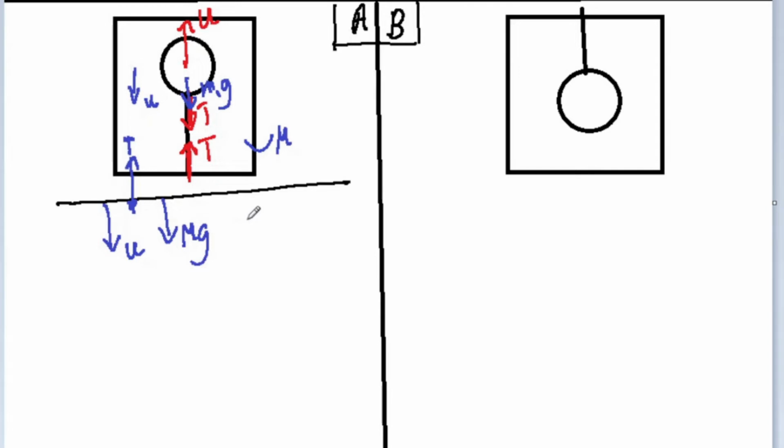So now we can write two equations. This ball is stationary with respect to this beaker. So the equilibrium equation for the ball would be U minus m1g minus T equal to 0. And what happens to the balance is the balance would move. So let's just say the total force W1, I'm going to mark it downwards, acts on this surface.